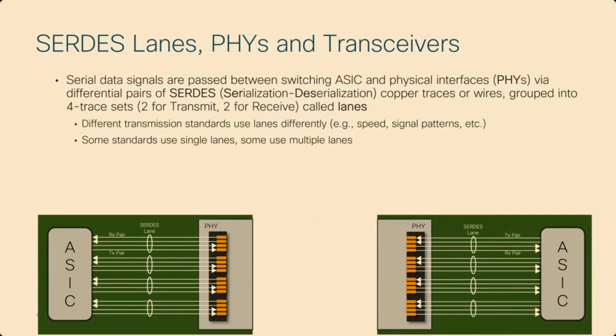So the lanes that I'm talking about are referred to by the term SerDes, which stands for serialization, deserialization, kind of like the term modem stood for modulation and demodulation. And basically, when you have these SerDes lanes, there's groups of 4 wires. And some standards for signaling will actually only have to use one lane, and some standards may have to use multiple lanes.